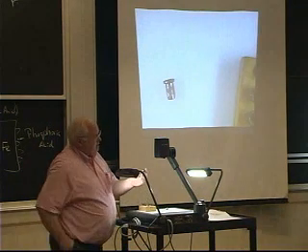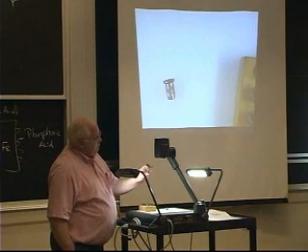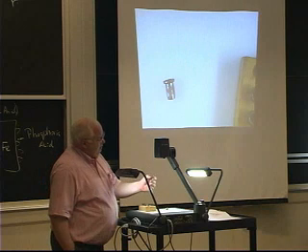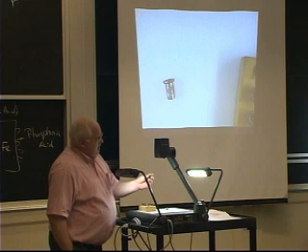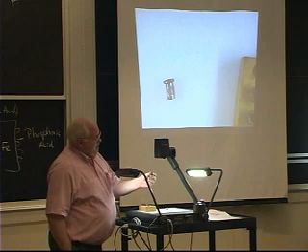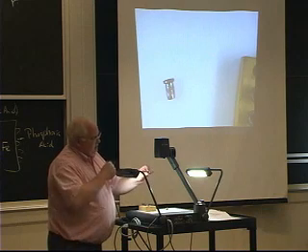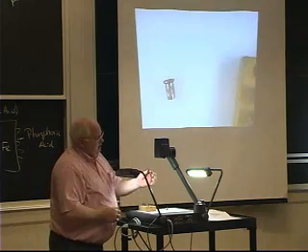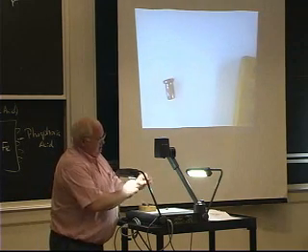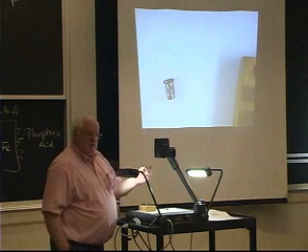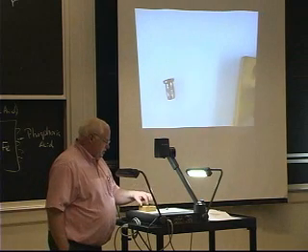This is all the pieces I got at a shop outside of Pittsburgh once. You might feel a little bit of lubricant on some of these, but they stamp it, cold form it in a die, and you'll see it's dished here, it's flat on the other end, and now it's sized to exactly the right size. The other one's just kind of rough cut.